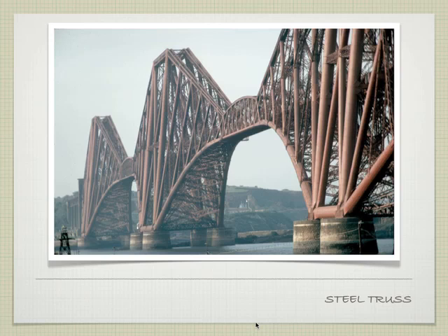If, however, I put a diagonal in here, and a diagonal in here, and apply the same force, these diagonals support that force. Likewise, I still have the support vertically. Does that make sense? It turns out that I actually don't need these pieces necessarily.